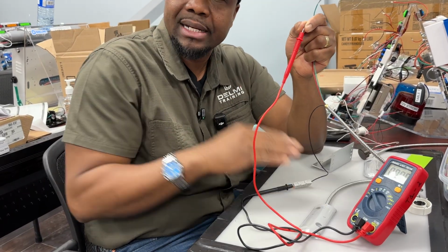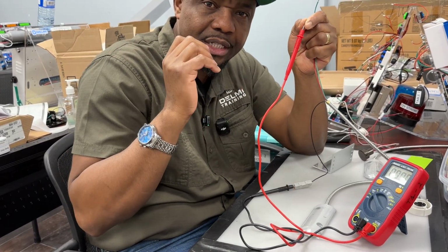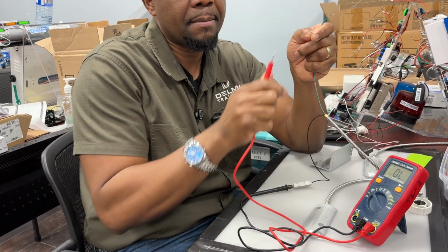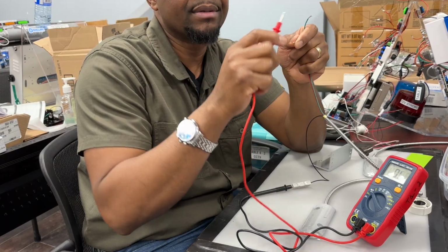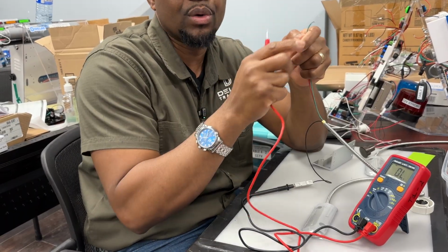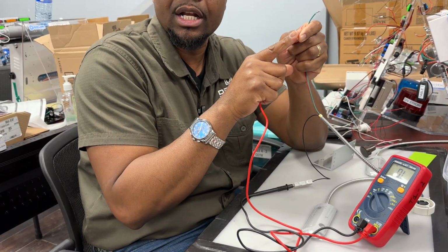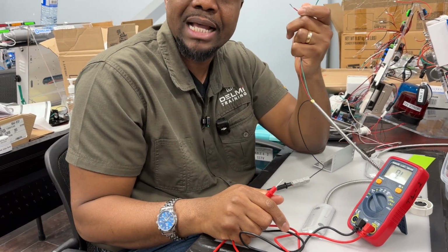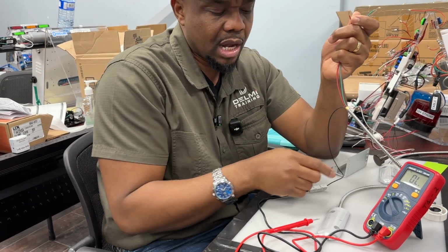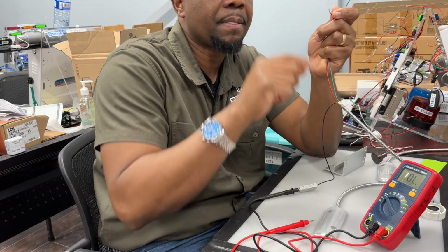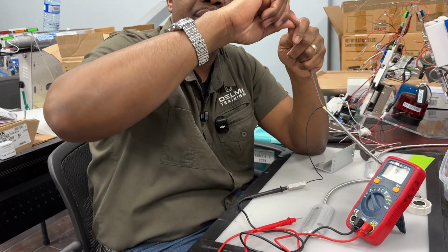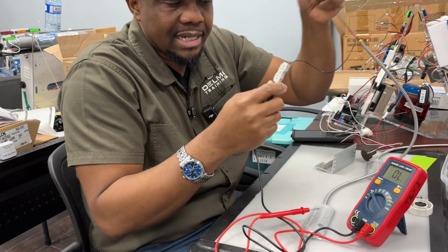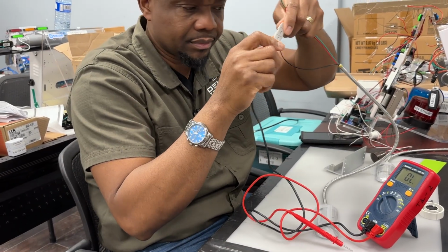This is what is beeping. So without the magnet, that is where you have to determine which one is your normally open and your normally closed. So there is no magnet there. The red one is beeping. The green one is not beeping. So in this state, the red is the normally closed. The green is your normally open. So that's how you're able to identify it. So now I know that my black is the common, the red is the normally closed, and the green is the normally open. That is just how I tested for this one.